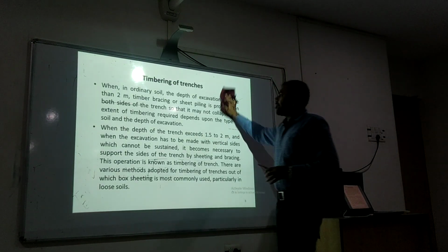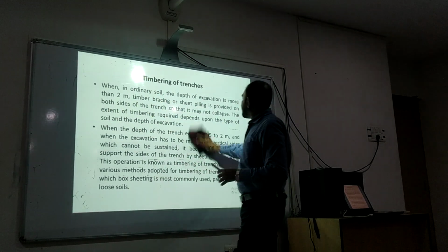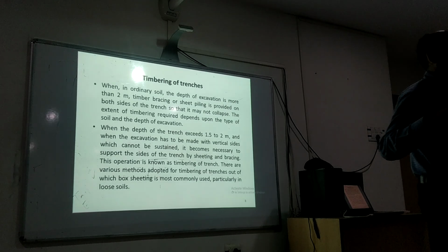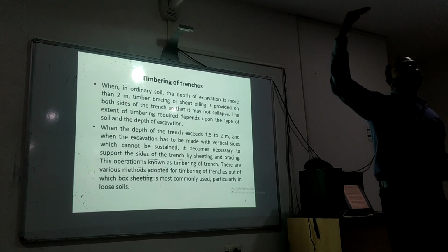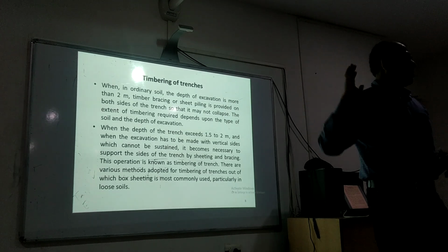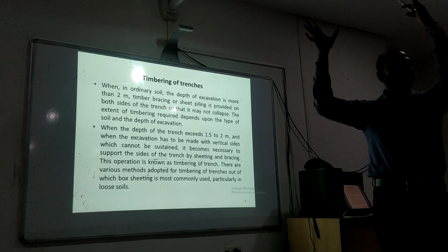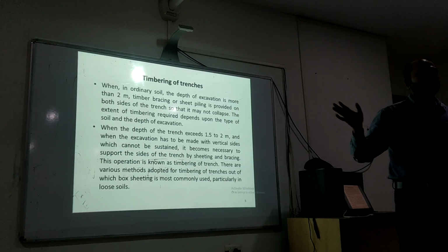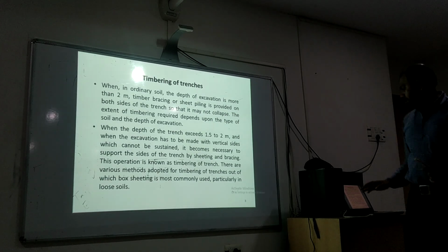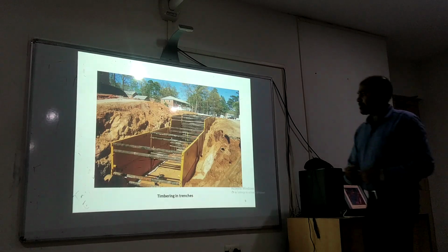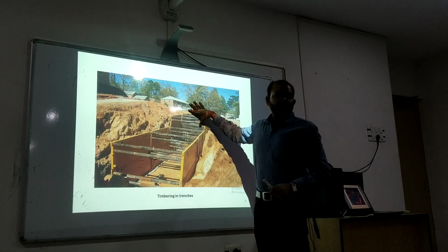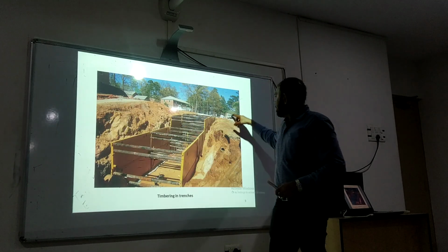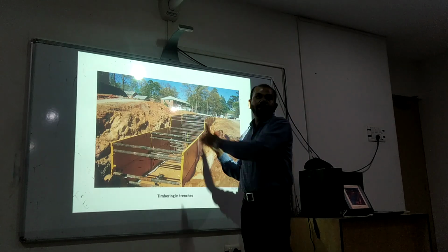Then timbering. What is this timbering? Timbering is basically, when the trenches are dug. Okay, जब गड्ढा किया जाता है, the trench is as deep as 1.5 to 2 meter. 1.5 मीटर 2 मीटर जो है deep excavation किया जाता है. So definitely from the side walls there will be pressure. Let me show you the diagram. Suppose this is the excavation. यहाँ पे देखिए, this is the road surface. Vehicles are moving. Suppose यहाँ पे देखिए, the lateral pressure will be there.